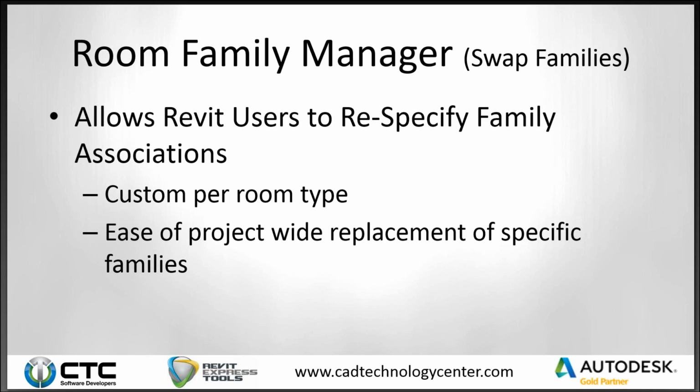So the next tab here is the ability to swap families. So if the designer uses placeholder content, just some basic design content that's dynamically created, over time, the actual drafters and the architects on the project are going to probably want to swap out that generic content for actual content that represents the real components much more appropriately. Actual chairs, actual desks instead of just cubes that are placed out in the model.